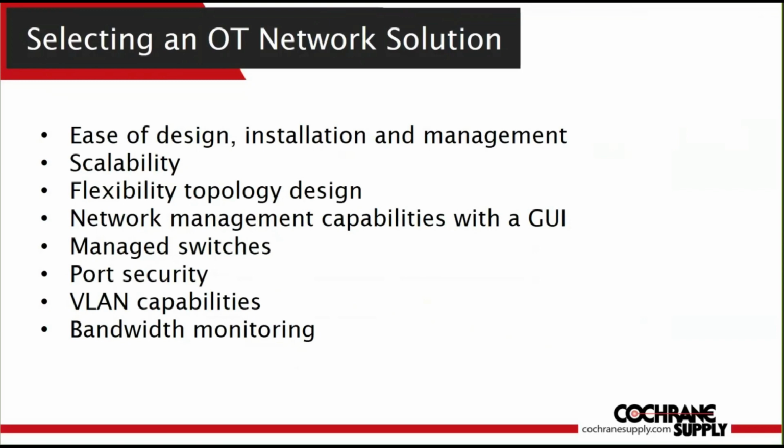You can set up VLANs because you have to anticipate that if not during the installation, maybe down the line, if you only have HVAC and say lighting on this network, you want the ability to add fire alarm, elevators and escalators, card access, whatever you want to add, because remember we talked about scalability. So you want the capability to set up VLANs at some point. And you also want to be able to monitor the bandwidth on your network.